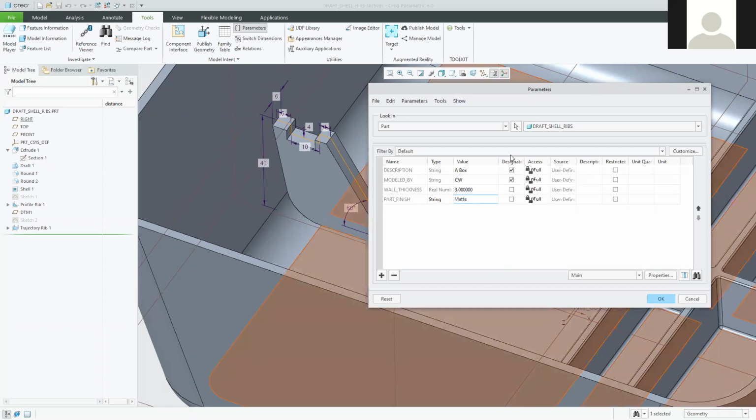So yeah, parameters can do both of those jobs, or they can do a job which, off the top of my head, I think we've done in another tutorial this week in a different CAD system. We added one in, so I'm adding another one in here. Purchased, as in, is this part that we're looking at bought in to the company, or is it manufactured by us? So purchased would be a yes/no question, and you would just set it as either yes, we buy it in, or no, we don't buy it in. So you've got that option as well. Parameters can keep all of that.